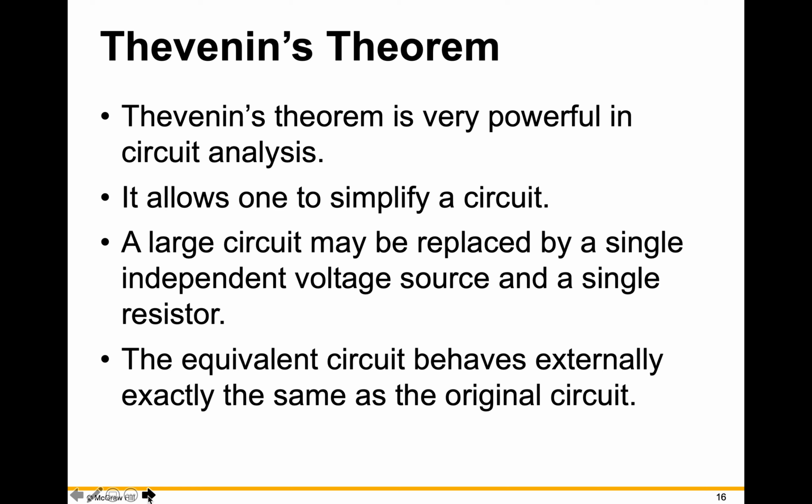So Thevenin's theorem is very powerful in circuit analysis because it allows you to simplify a circuit down to a single voltage source and a single resistance. And that's huge, particularly if you're looking at things like how much power that circuit is going to deliver to a load, which is one of the main applications of the Thevenin equivalent. So we can take a big circuit and replace it by a single independent voltage source and a single resistor.